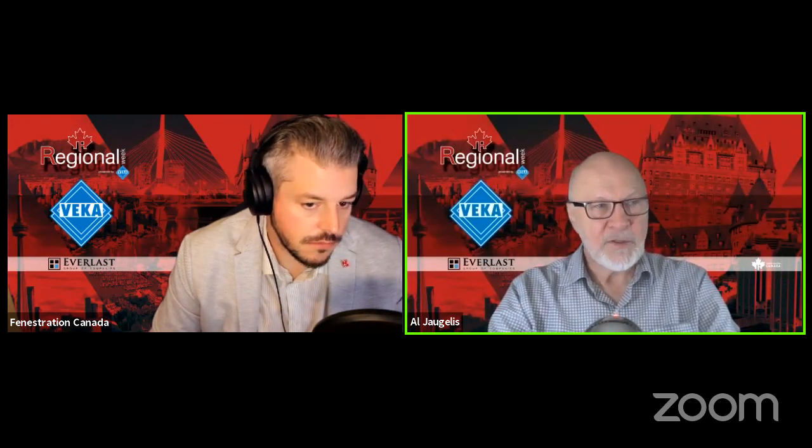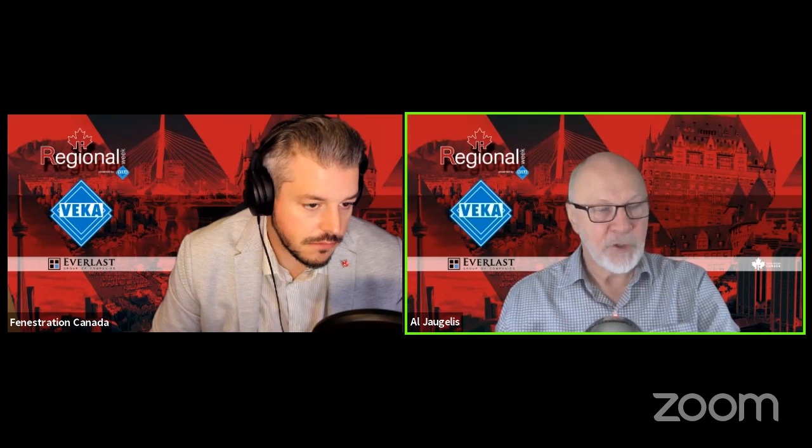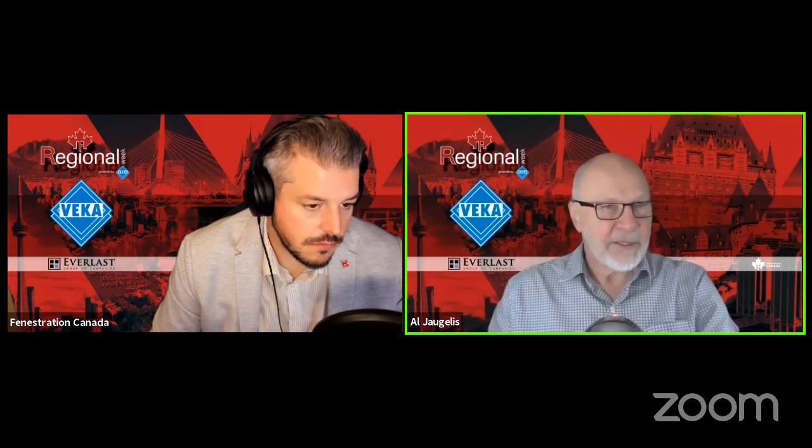If you mentioned that these are waterfront homes, the rough terrain only kicks in when you're a kilometer away from the shore. So is that subdivision going to go farther inland than a kilometer? Because if it's within a kilometer of the shore, it's going to be open terrain anyway. Okay. But it's a good question.